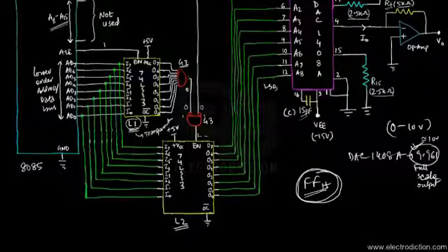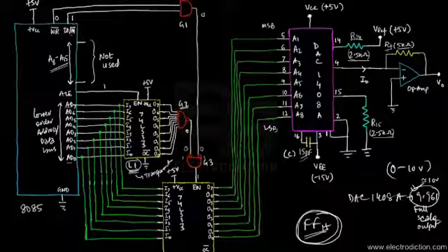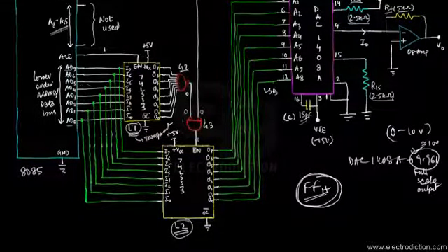So as soon as the latch chip L2 is enabled, now by this time, immediately before the L2 chip gets enabled, the lower order address or data bus, that is AD0 through AD7, gets ready to output the data. Since it's an input output operation, as soon as the logic level on the input output memory bar pin goes to logic 1 and the write bar pin goes to logic level 0, at that very moment the lower order address data bus stops sending the address FFH, and now it is sending data. So it has become the data bus, now it's behaving as a data bus.